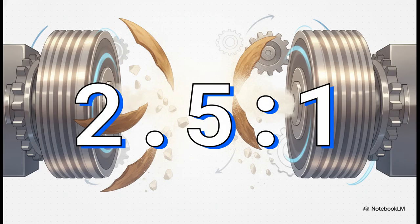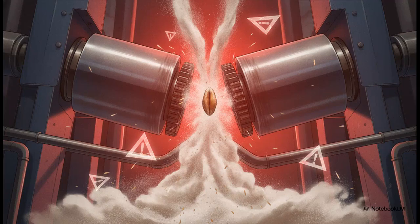As the wheat passes through the nip, the slow roll holds the tough, moisture-conditioned bran layer steady, while the fast roll applies a forward vector force to drag the friable endosperm away. This precise differential calculates exactly enough force to detach the starch without slicing the tough bran layer into microscopic, unsiftable shards. If that 2.5 to 1 ratio narrows, we have a standard maintenance failure known as differential drift.